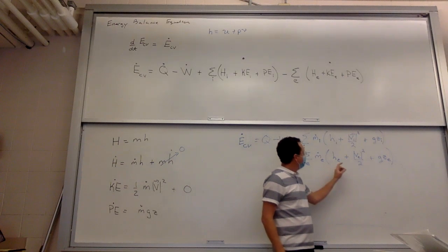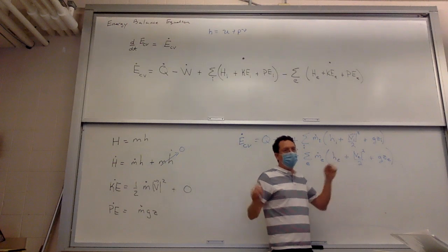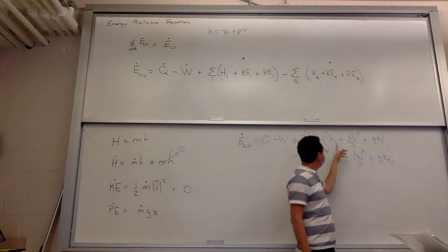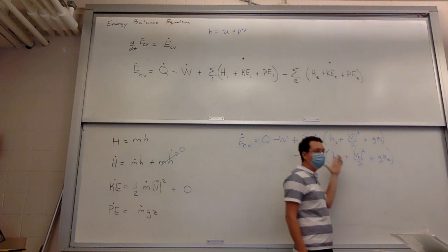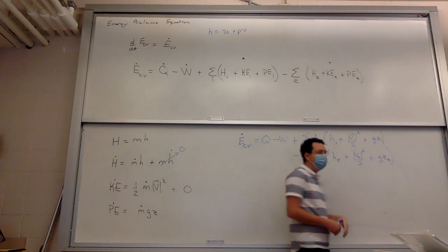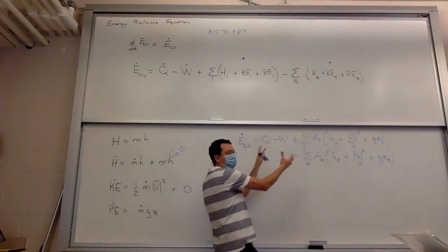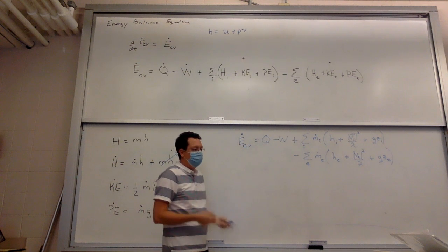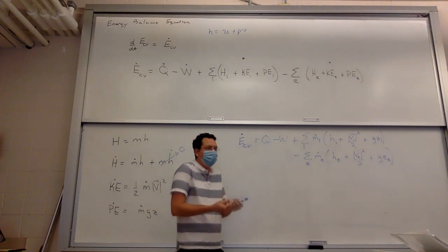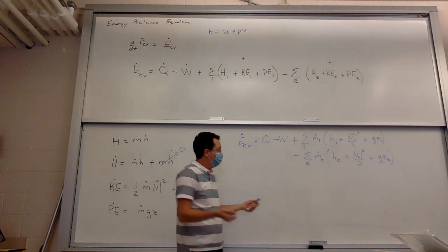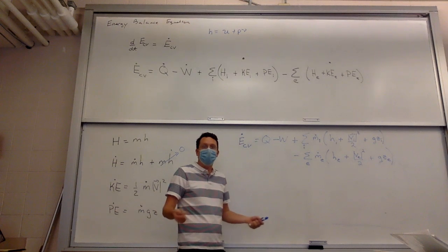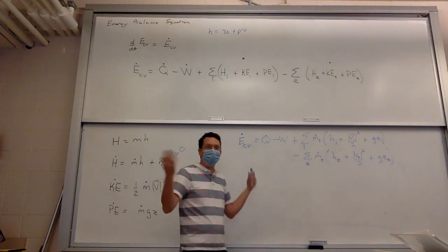Now, in most problems, in most situations, you can drop kinetic and potential energy. And ultimately, the quantities you're looking up are enthalpies. I mean, it's the same kind of stuff we've been doing. It's just you want to pull it together this way rather than using the first law for closed systems. So it's the same as far as the procedural steps you're going to have to do to solve a problem. Same thing, lay it out, identify what you have, identify what you want, go to the back of the book, get the numbers you need, given a certain pressure and temperature.